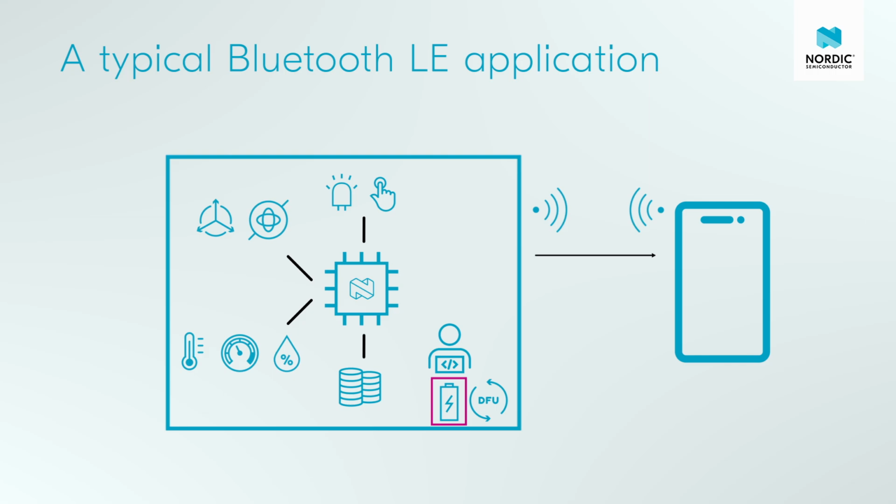In summary of this video, we learned a way to get an estimation of the power consumption of a Bluetooth low energy application using the online power profiler. And we also learned a way to measure the power consumption using the affordable PPK2. And then we applied some basic tricks to optimize our application for low power, which is basically disabling logging, changing the advertising interval, and requesting connection parameters. There's still a lot of things you can do to further optimize your application, and that brings us to the next video,